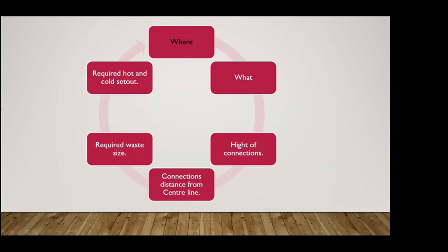And then it's on them to pay the cost. So you do have to be a little bit careful, and just basic stuff like making sure the cold's on the right, hot's on the left. Some places things can be back to front. Sometimes you make mistakes. You're looking at it from the wrong side of the wall, there's no jib there, you get confused and you do it the wrong way. So sometimes you can just flip the hoses on the mixer or something and cover it up. No one knows. Other times you've got to fix it properly.